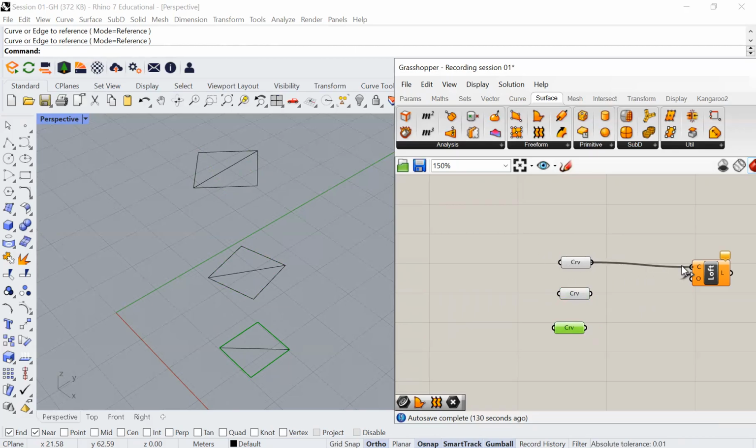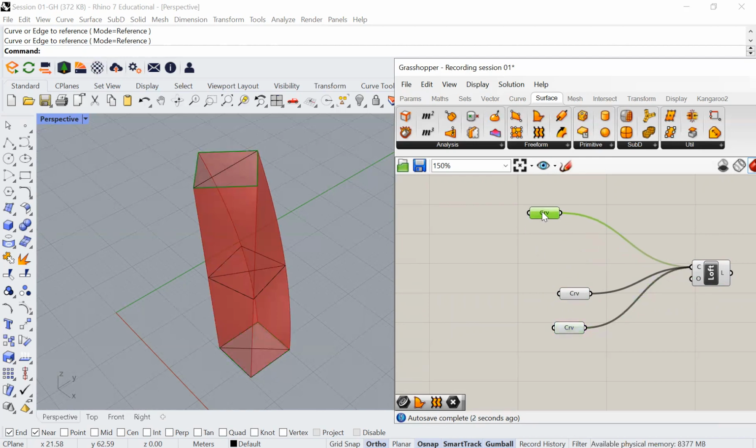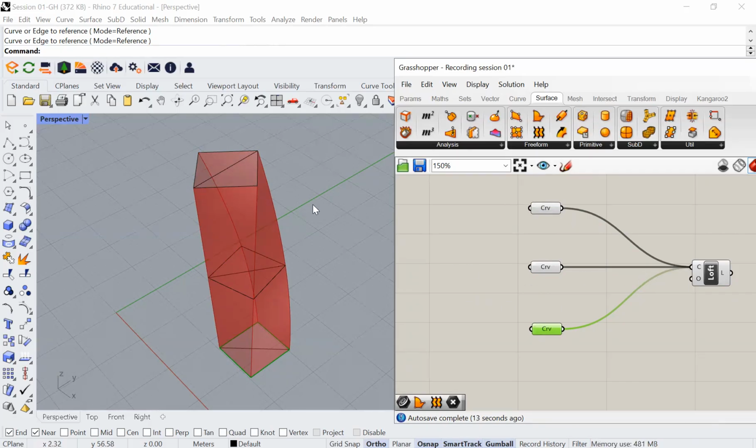And you'll have the same result, okay? So if you hold shift while you are connecting, you can connect to three icons, three components, but you need to use shift when you take the wire from the C input, okay? So as I said, if I want to rotate this, but I don't want to rotate it manually each time, and also I want to experiment with having different angles, maybe scenarios that I didn't think about in my design. So I want to have that flexibility.